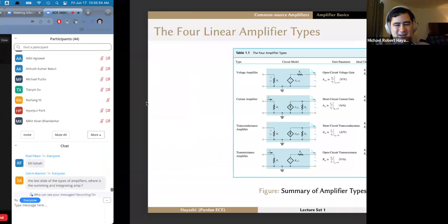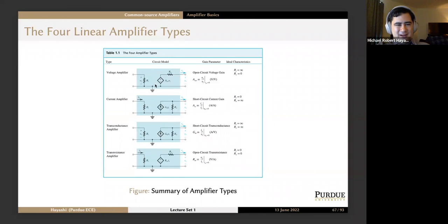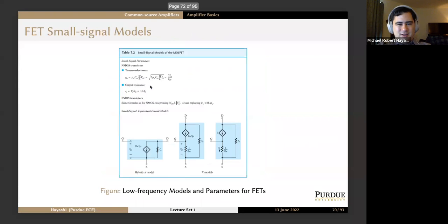And if you want to have an integrating amplifier, you would have feedback that includes capacitance in it. So this is like the model of the amplifier itself, like the internals of the op amp, not the overall circuit structure that goes into making an inverting or summing or integrating amplifier. Hopefully that answers that question.